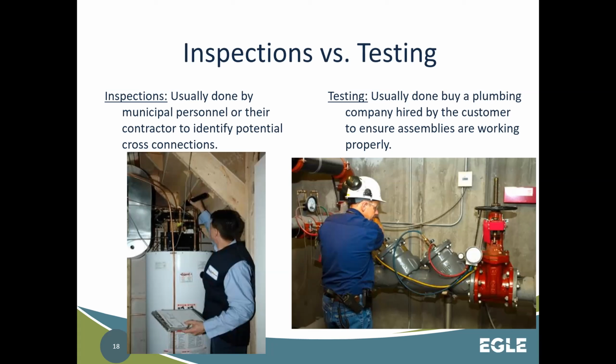Now, Michigan does not recognize, in industrial and commercial settings, a backflow assembly being repaired by anyone but a licensed plumber. We do not recognize the ASSE repair certification. Okay, just so we're aware on that. But testing has to be done by an ASSE 5110 certified tester. Sometimes those people are not licensed plumbers, and they don't have to be.